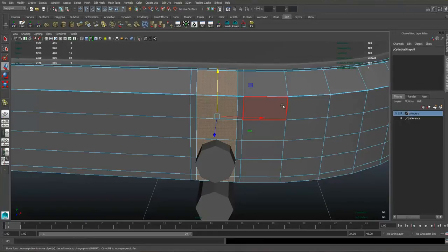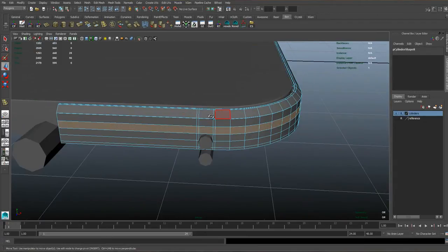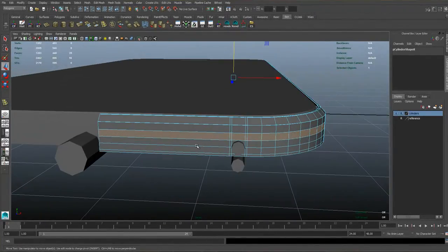Just hit those. Obviously there's a backwards and a forwards arrow, so if you hit the forwards arrow, it should increase your selection amount. So you can do this to anything. Select any ring of geometry or of faces, and then hit Shift and full stop, or Shift and the right arrow, and it should increase your geometry like this.